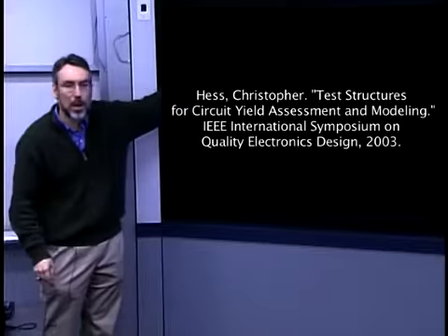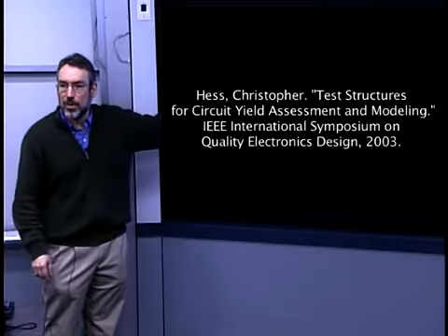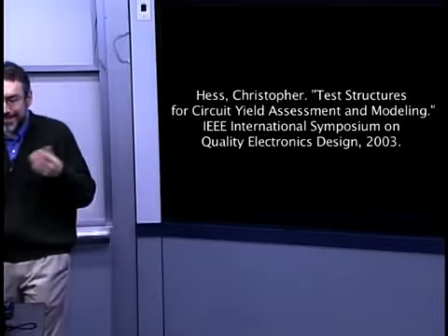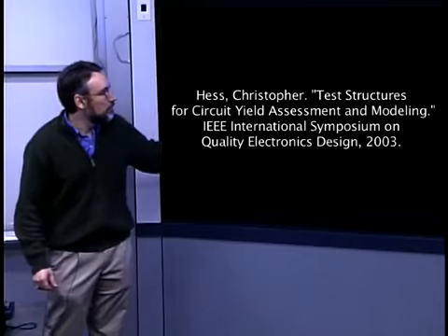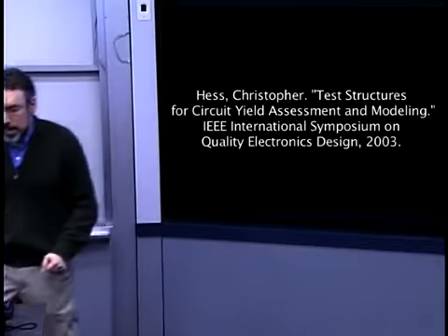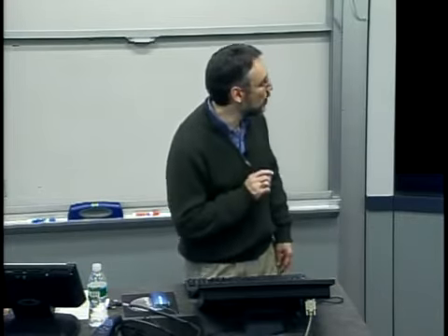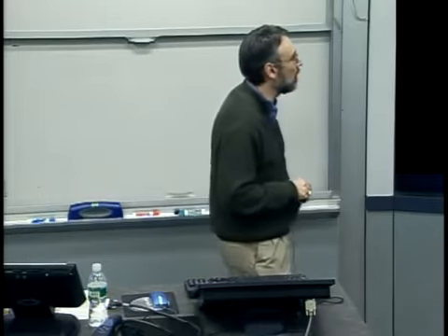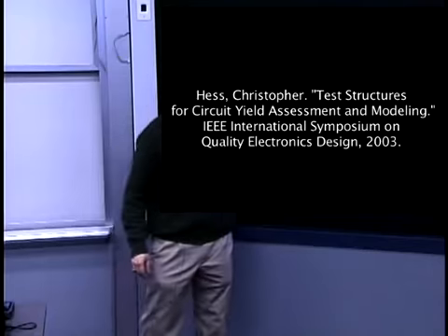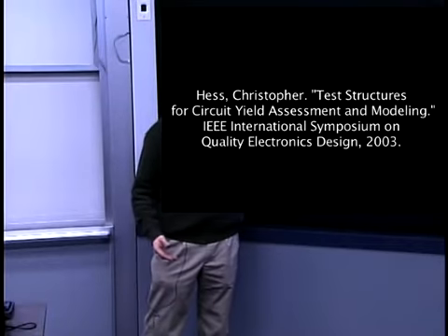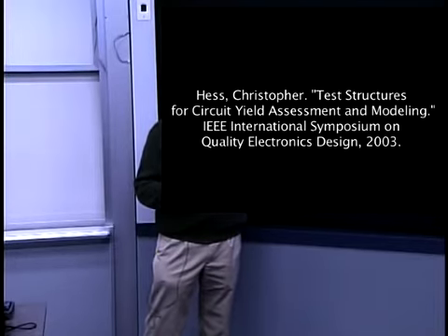We'll talk about yield modeling and some of the technologies that are used for characterizing statistically the point defects, particle defects, and some of the strategies used for optimizing or minimizing impact on circuits. But what is becoming much more important, and we mentioned this on Tuesday as well, is parametric control. And in some cases, even these defect controls turn into parametric control problems if what I'm worried about is not so much yes-no functionality, but changes in the resistance of lines because of the presence of defects.